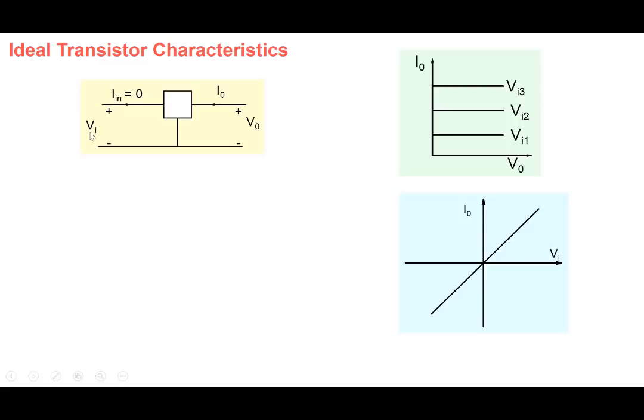So remember, in our discussion of triodes and transistors, we said output current is sensitive to voltage applied across another pair of terminals, so transconductance, while output current is not that sensitive to output voltage here, which is the output conductance. So these are like the transistor characteristics. This device has finite transconductance, but output conductance is 0, so obviously transconductance is very, very high compared to output conductance here. So this is the element, and we are saying that this is like an ideal transistor